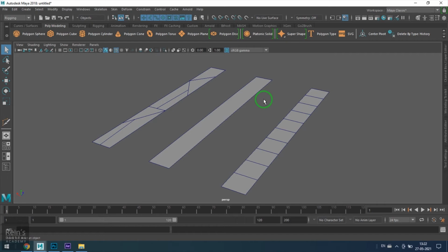For example, if the model you're making doesn't deform or get animated, like when you are modeling a room with a tube light or a table which doesn't move or deform, we only add lines which can build a shape. But if the same table has to be deformed, we see what kind of deformations that table will get, and then we plan the flow accordingly.